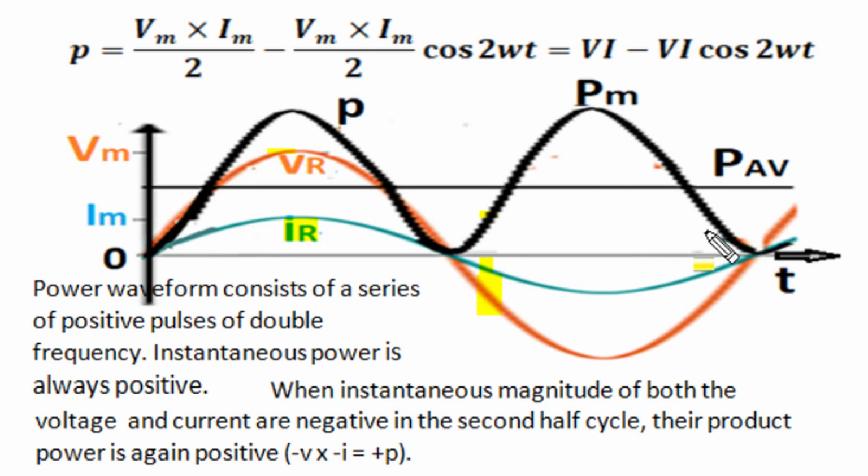In both cases, collision among drift moving electrons generates heat, or electrical energy gets converted into heat energy, and the rate of energy converting into heat is known as power, and power is fluctuating but in one direction only. When the magnitude of current is small, power magnitude is also small, and when current attains peak magnitude, power also attains peak magnitude. And this double frequency variation of power has a non-zero average value, the product of RMS voltage and RMS current, and a double frequency cosinusoidal variation.